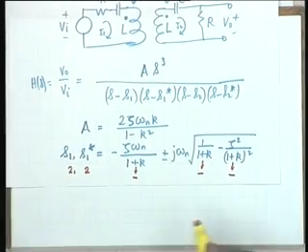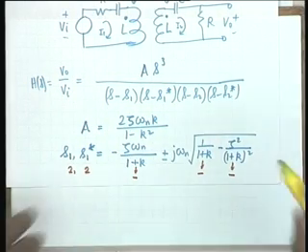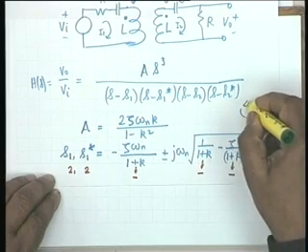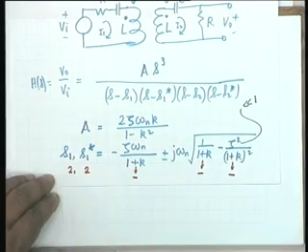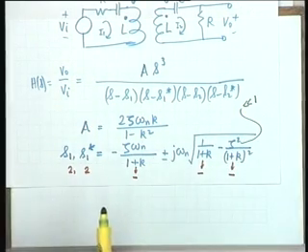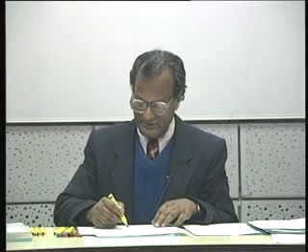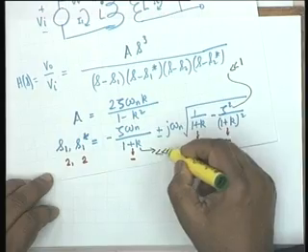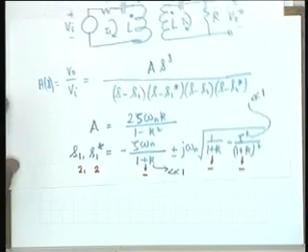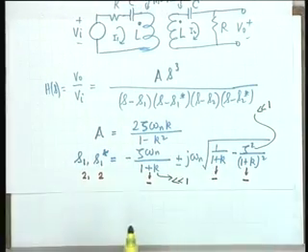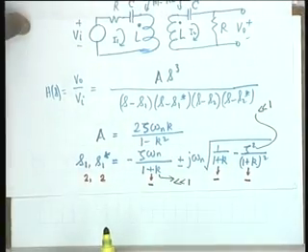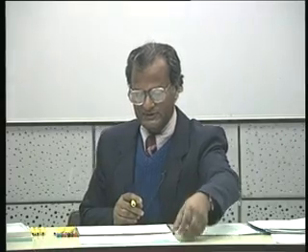So, these were the poles, and then at this point of discussion we made a certain approximation. We said that zeta squared is much less than 1. That means it is an underdamped case. We also assumed that the coefficient of coupling k is also much less than 1. That is, the two coils are loosely coupled to each other. Under this assumption, the poles.